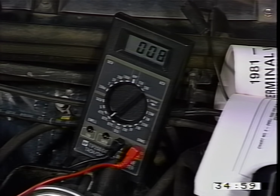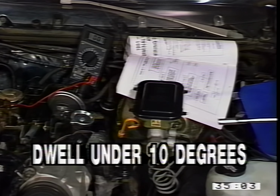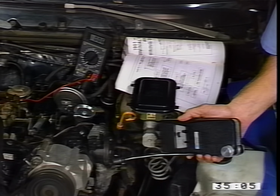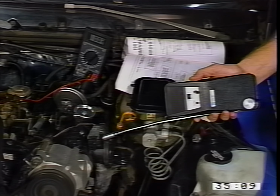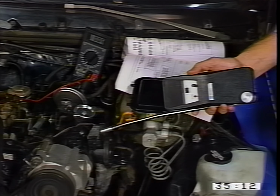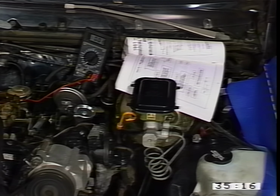Another possibility: dwell will be under 10 degrees. You're directed then to check for a leaking air switch valve to the exhaust ports at 3,000 RPM. If no leaking is found, then you're instructed to service the carburetor, including its adjustment. This could also indicate a vacuum leak.